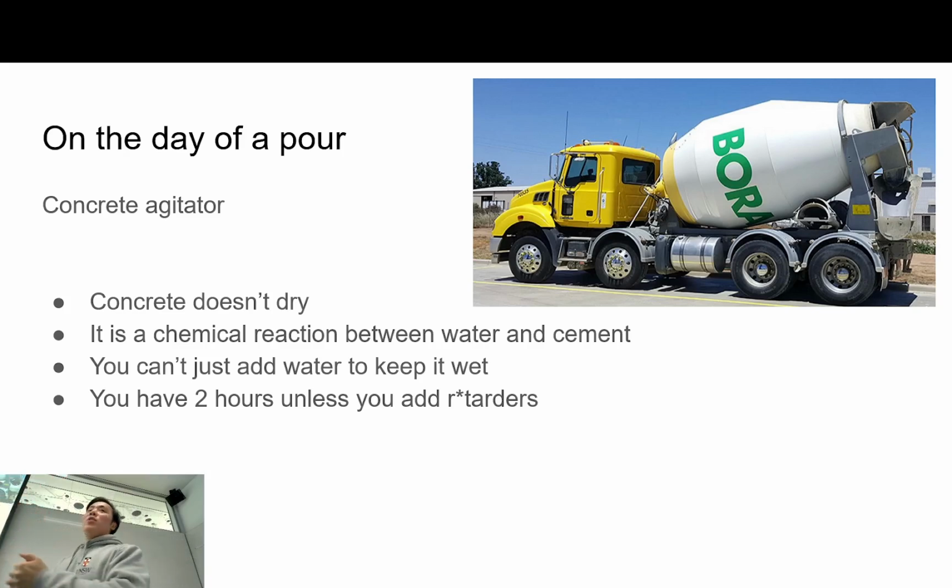which will prolong the drying process. There are also other things that you can add to make it set faster, and depending on the type of work you do, you might need to have it set faster. But usually 2 hours is good because the truck needs to drive to site and then it might need to wait a little bit before it can pour the concrete. So you need some time.